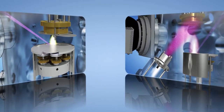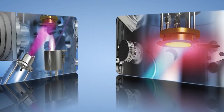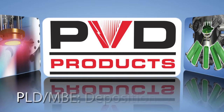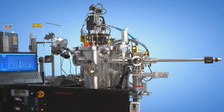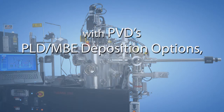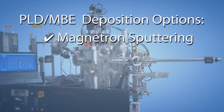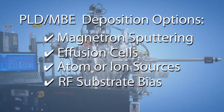PVD Products PLD MBE and several of our other PLD systems are highly customizable and can be built with other types of deposition processes fully integrated inside the vacuum chamber, along with the pulsed laser deposition process. Our PLD MBE deposition options allow you to complete multiple types of depositions all within one chamber, making your work faster, easier, and reproducible. Deposition options include magnetron sputtering, effusion cells, atom or ion sources, RF substrate bias, and high-pressure RHEED.